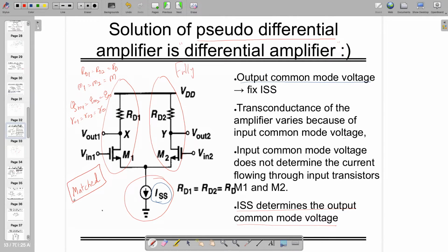The circuits are matched, having equal multipliers and equal fingers. Whatever you are doing with M1, it's the same at M2. It's just control C and control V. It's very simple, right? And this is what we are doing because of one fact. In the equation y equals mx plus c, m has to be the same, where m is acting as gain over here. And for a non-linear circuit, you might have different gains at different frequencies. Like at the fundamental, you want m for the left-hand side circuit the same as the right-hand side, and the same for the gain at all other harmonics.